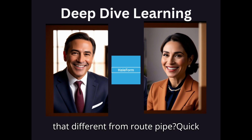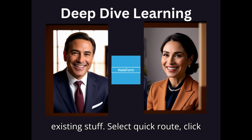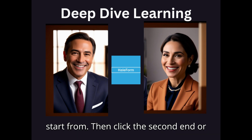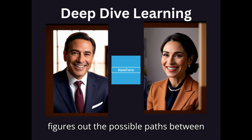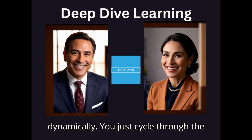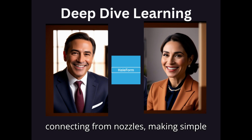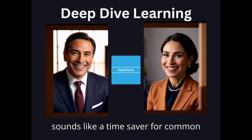Okay, last creation tool before we talk modifying. Quick Route. How's that different from Route Pipe? Quick Route is all about speed for connecting existing stuff. Select Quick Route, click an open end, a nozzle, a straight pipe, or even a surface-mounted component to start from. Then click the second end or nozzle you want to connect to. Smart 3D figures out the possible paths between those two points and shows them dynamically. You just cycle through the options, pick the one you like, click Finish, and it builds the connection automatically. Great for joining runs, connecting from nozzles, making simple branch connections quickly. Definitely sounds like a time saver for common connections.